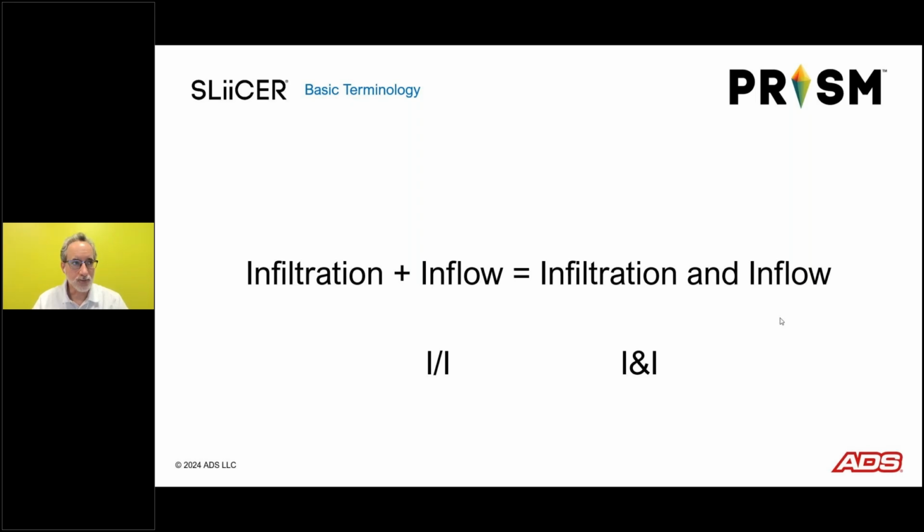I find that when I work with coastal area communities, they are typically more laser focused on infiltration than some of the other communities more inland, because they're often flatter. They're having to pump flows multiple times before they get to the wastewater treatment plant, and it's a significant cost day in and day out. So infiltration and inflow, I&I.